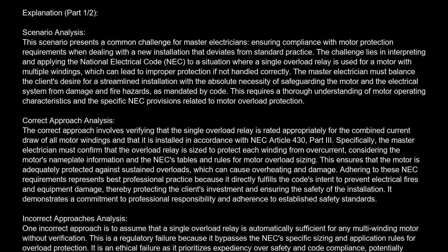The correct answer is B. Verify that the single overload relay is correctly sized to protect all motor windings from overcurrent, in accordance with NEC Article 430, Part III, and confirm its proper installation.